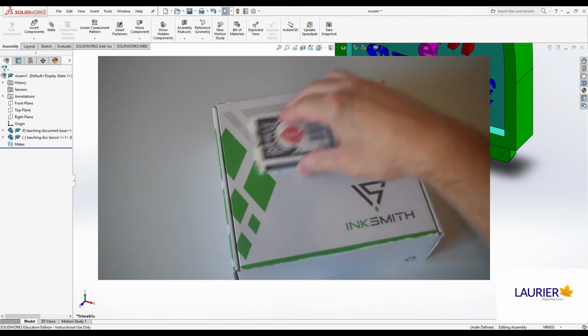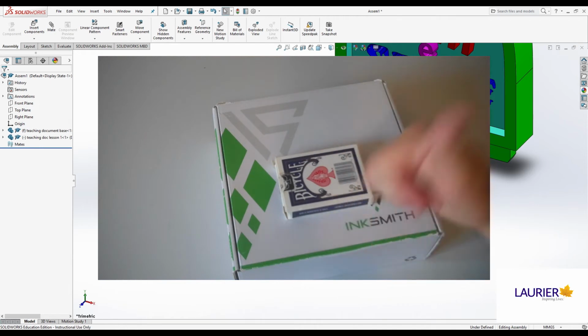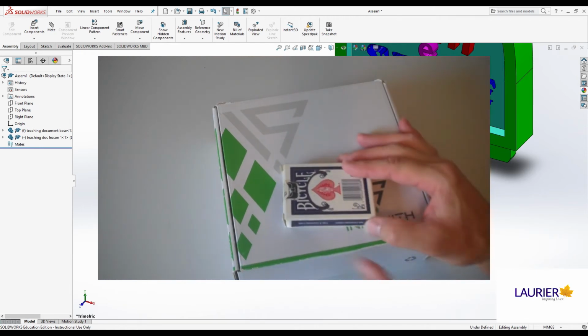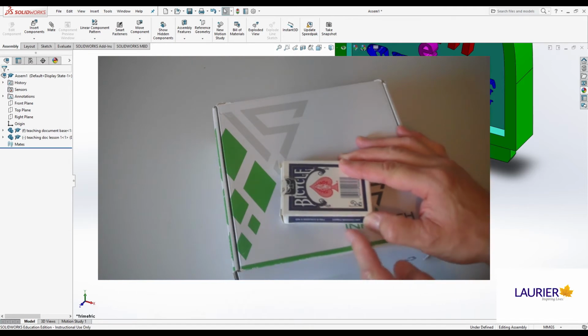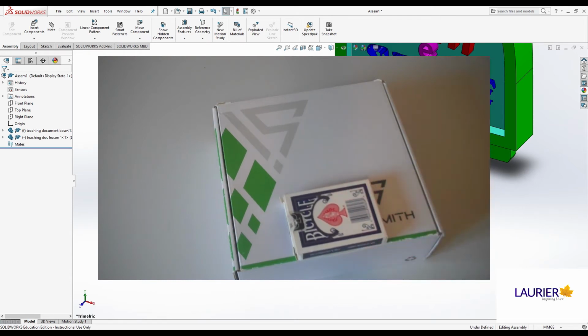You can slide the second part around that plane and you can rotate it, but you can't lift it off the plane. One degree of freedom is controlled. If you then add a plane-to-plane mate between the side of the part normal to the first plane and a plane on the other part that is also normal to that first plane, the part will move so that the second pair of planes is also coplanar.